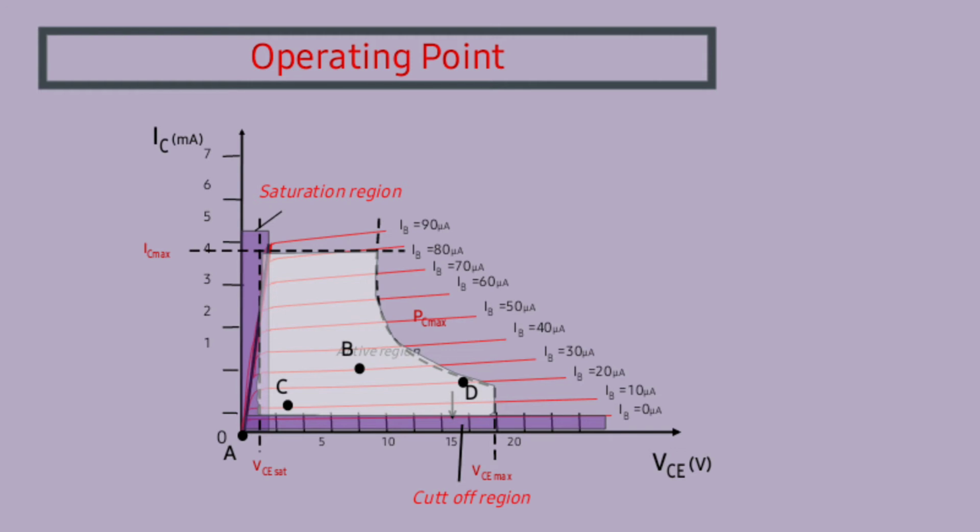For transistor amplifiers, the resulting DC current and voltage establish an operating point on the characteristics that defines the region that will be employed for amplification of the applied signal. Because the operating point is a fixed point on the characteristics, it is called a quiescent point, or simply the Q point. By definition, quiescent means quiet, still, inactive.